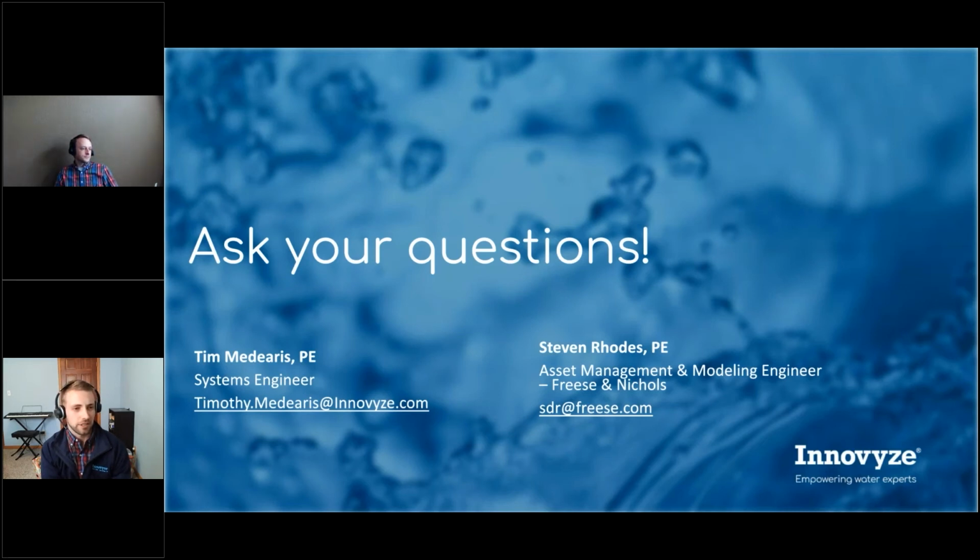Perfect. From Spencer, another one here. Did you have any challenges in getting the model to initialize? Some of the troubleshooting you did in that initial model setup? Yeah, we did initially. Like that storage basin example, that one gave us a real hard time on initialization because we didn't really have that dummy gate system set up yet.